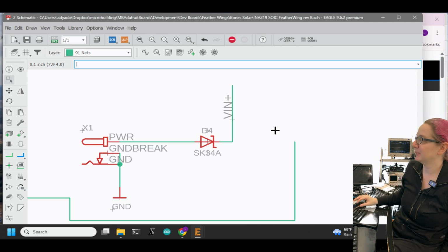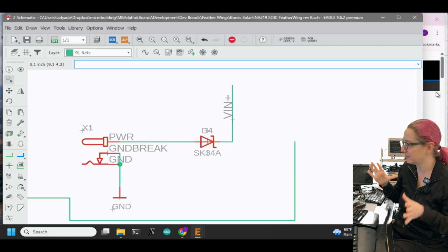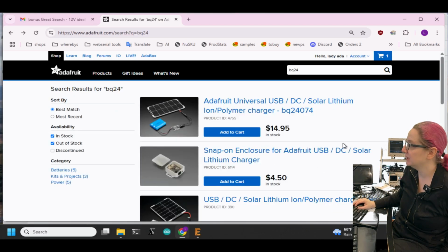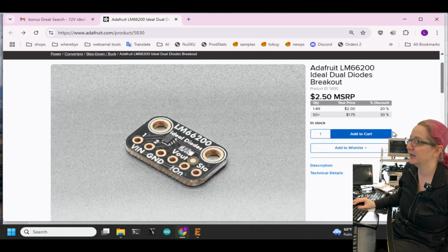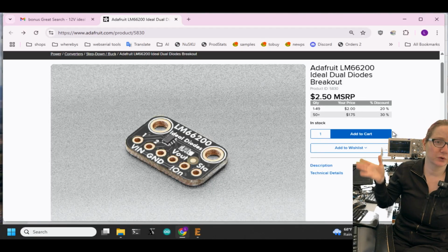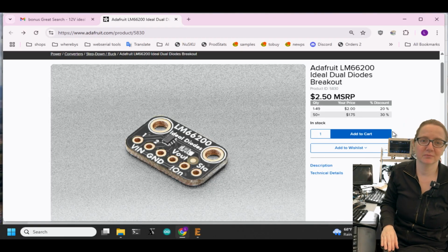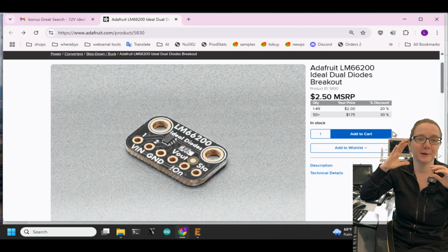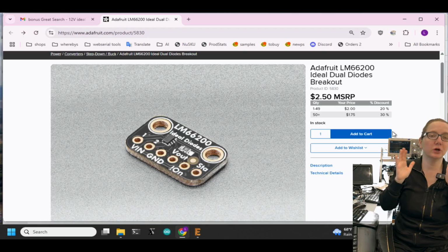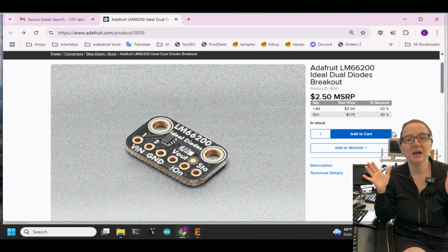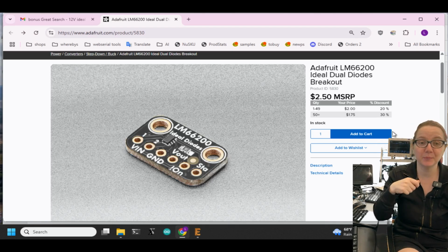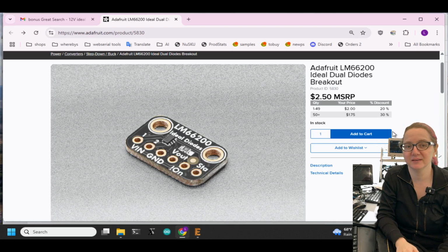Maybe it's okay to lose a little bit of power, but as I'm doing more solar stuff, I want to find a better solution instead of just using a Schottky diode, even though it works perfectly. And so one option is to use what's called an ideal diode. An ideal diode, you can look on educational electronic learning sites about it. You basically take two FETs together, you have a little controller, and it turns into an ultra low dropout ideal diode where current only goes one way. There's only forward voltage in, and you can also enable and disable it because it's like an active ideal diode.